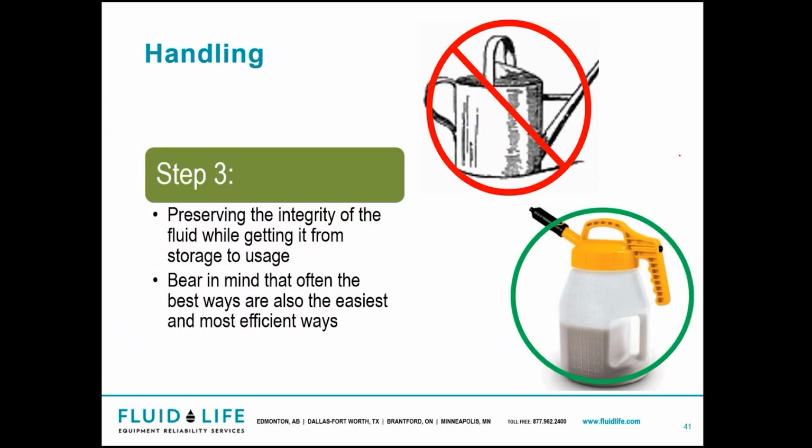And then basically where it comes back to, now that we have all our good oil stored, we have everything perfect, right? We've eliminated every sort of contamination source possible. Well, now we need to keep it clean going from storage to equipment. These oil safe jugs are great, whether you use these ones or any variation of them. You can make your life a lot easier just by having the proper color-coded oil system in place.